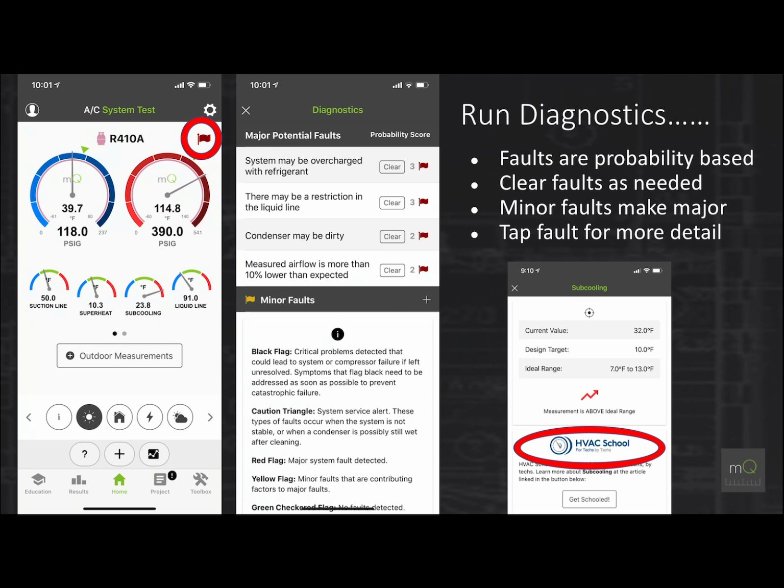If you run into problems, you're going to see a red flag in the upper corner of measureQuick, and that's going to tell us that we need to run the diagnostics, which just means tap on that red flag. measureQuick is going to show you faults. The top fault is the most likely problem. In other words, in this case, most likely we have an overcharge of refrigerant.